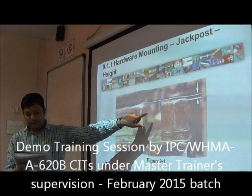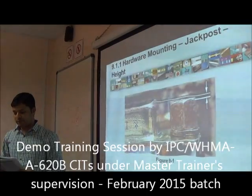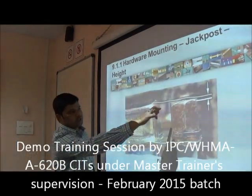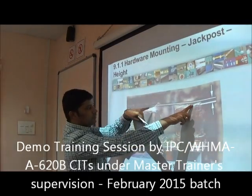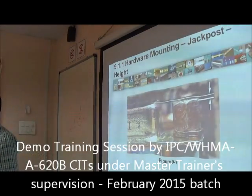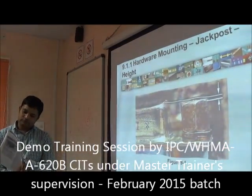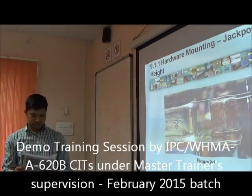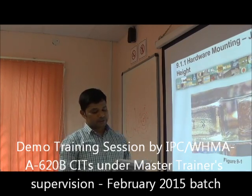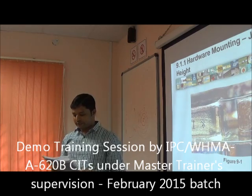See, the hardware stack up for a mounted connector may be varied in order to locate the face of the jack post flush, and it can be plus or minus 0.5 mm. This jack post face from the connector face can vary 0.75 mm. So as per the acceptability class 1, 2 and 3, the jack post face is flush plus or minus 0.5 mm with the face of the connector.